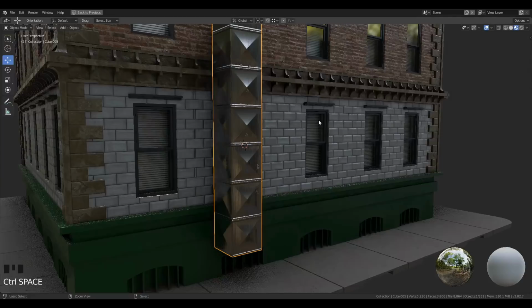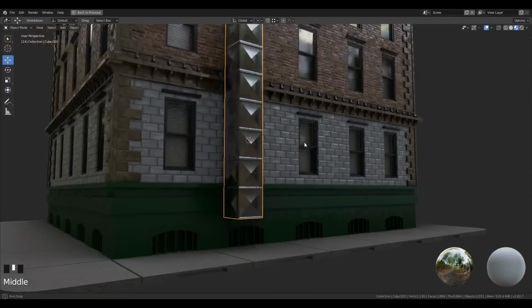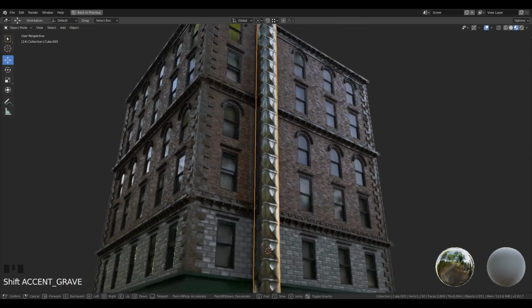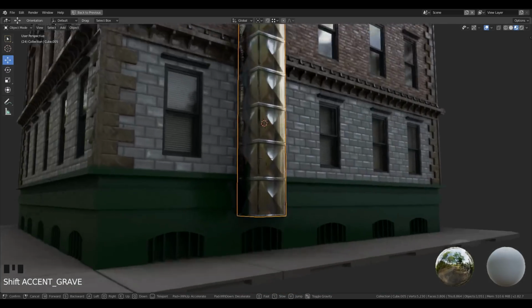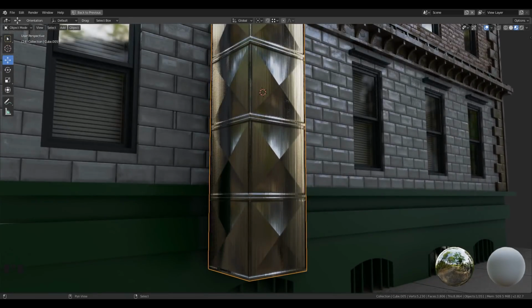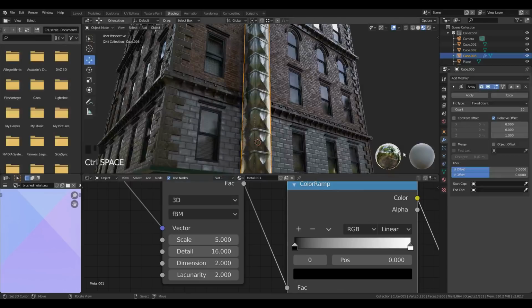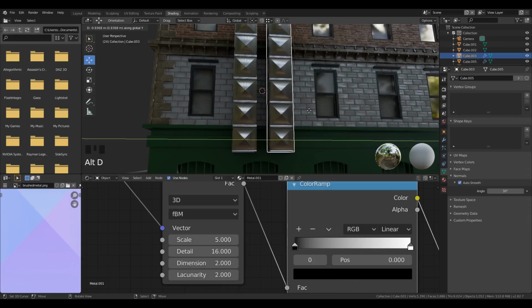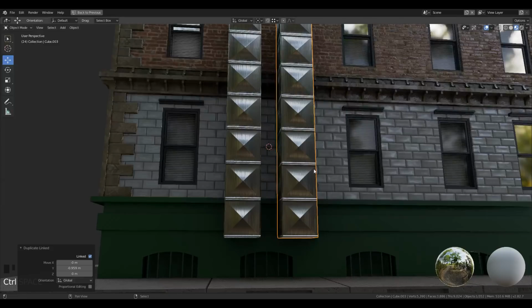One more trick, if you apply shade smooth to it, it will apply some curviness to the model and will add more shading curve to it. So you can use it and can get some pretty cool results. But I'm going to apply auto smooth, which can give sharp edges according to what value you give for the model. Now just duplicate the mesh and make its instance.